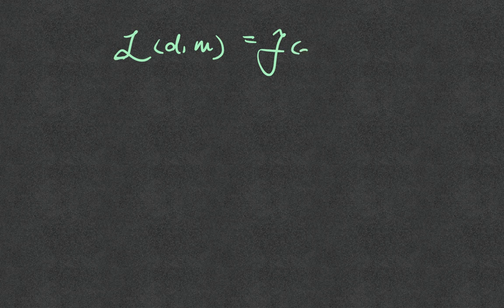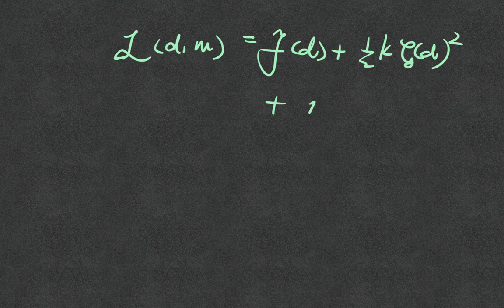Now, what is the first option? What is the third option? The third option is the following: I will use both the penalty and the Lagrange multiplier. This is actually a niche method, but very common in contact mechanics. In which case, I will write, maybe I put an L, I just want to use a different one, and then I will write F_D, and then I would have the penalty term, but I would also have the Lagrange multiplier.